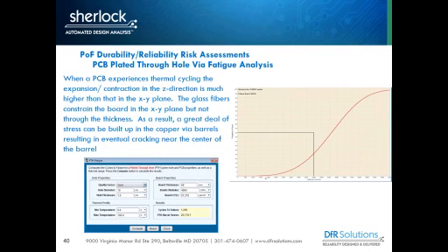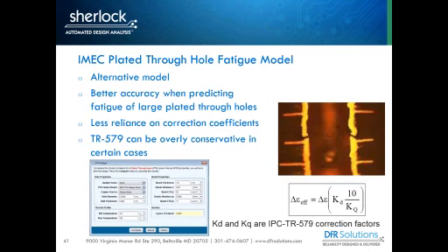In fact, it's 3 to 4x higher. Even though it's a fiber reinforced material, it doesn't really have fibers in the Z-axis, everything's in plane. So there's not a lot of constraint in the Z-axis, so the epoxy wants to expand, and you're going to get a very high CTE in the Z direction. That causes a lot of stress on the copper vias.